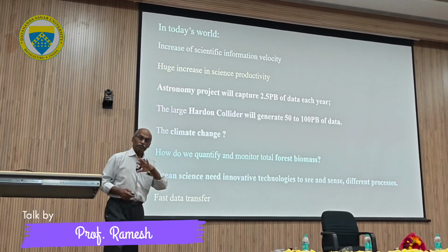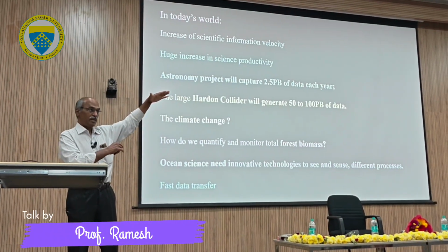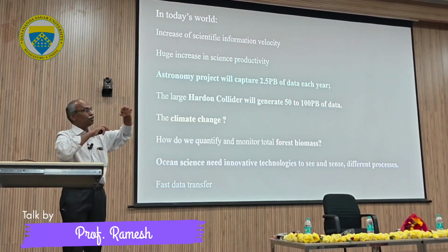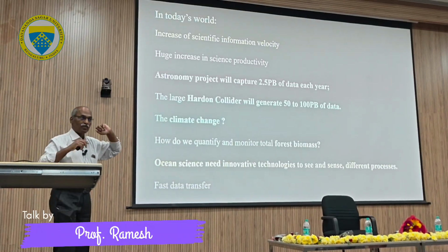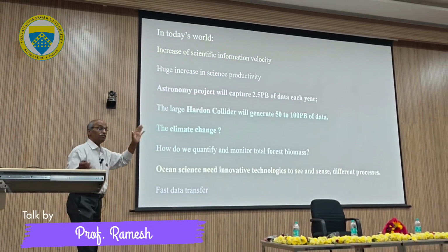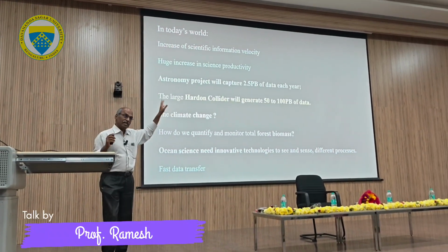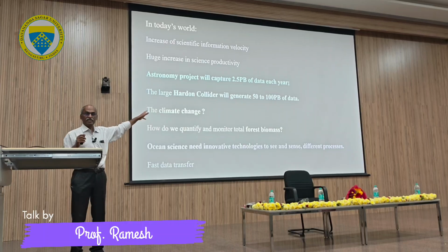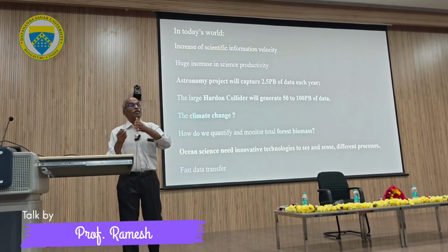I hope you understand that glasses are in the amorphous state, which is a high energy state. You can give some energy to cross the barrier, and they can go to the equilibrium state, that is the crystalline state. And these two states have a huge property difference. There are many glasses that we listed in some of the previous slides. These glasses will not have that kind of property difference.